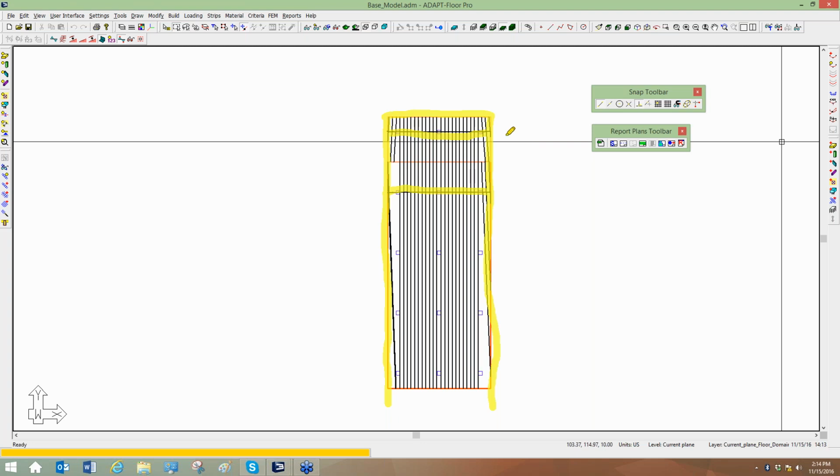It's perpendicular to the support line, and the design sections are cut over that tributary panel, if you will. So the panel that the program is creating is right there, and it's basically taking half the distance between this support line and the support line below, and it's taking this as the tributary.